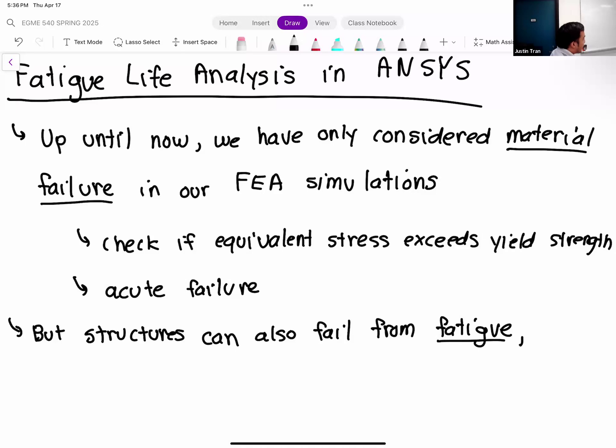And what that basically means is that, over the course of time, as a structure experiences different amounts of loading, we call them loading cycles. And so, cycles where the structure is loaded, unloaded, it's loaded, it's unloaded, right? That's going to gradually weaken the material over a long period of time.